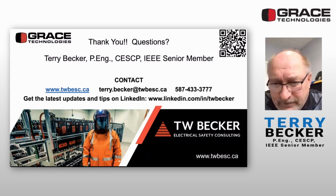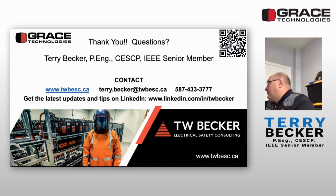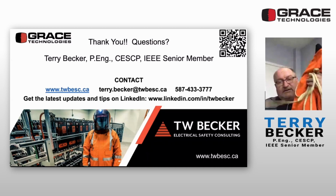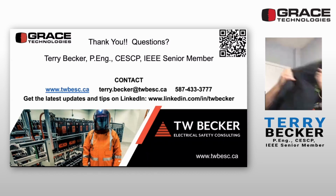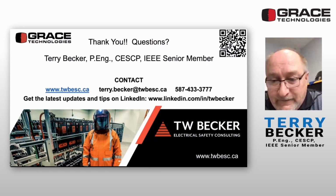All right. What was it, Oberon escape strap. Google it, you will find it. Oberon escape strap. This is an escape strap vest with a 10-foot Kevlar non-conductive strap that will yank away 1,000 pounds, right? And then you can extend this escape strap so it's available as an over vest, right? And then it's also available in their arc flash suits. So it's embedded in arc flash suit jackets now. This is patented. No other vendor will have this escape strap. This is innovation in electrical safety. This is what you can use for emergency release of an electric shock worker, or again, for higher low voltage with a standby. The standby could then grab this and remove the person to a safe area, then to apply first aid and CPR.